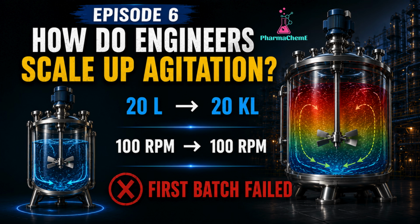But the first commercial batch doesn't. The reaction takes longer. Temperature becomes non-uniform. Mixing is no longer the same. What went wrong? After all, 100 RPM is still 100 RPM. Isn't it? By the end of this episode, you'll understand why experienced process engineers almost never scale up agitation using RPM alone, and how they decide what to preserve instead.